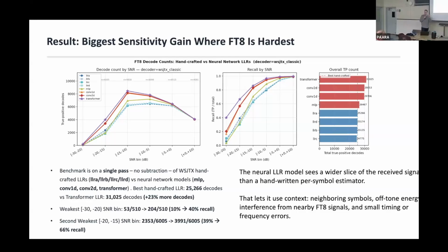So at that level, they already do a lot to achieve pretty much the best. They use what's called non-coherent block demodulation, from a paper in about 1993, which is basically continuous phase FSK over intervals. That's exactly what an FFT gives you.